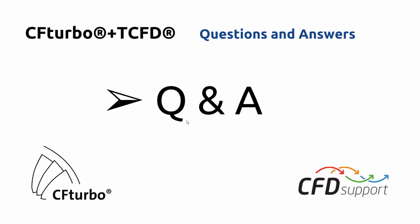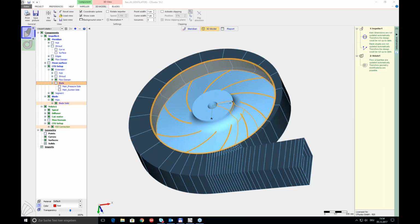Okay, thank you, Oliver. The next question is also for Oliver, from Mike. Is an airfoil profile blade available in CFturbo? Yes, in general I can say yes. It is especially useful for axial fan design, because there one can apply airfoil design theory. But it can also be applied in centrifugal or radial fan design.